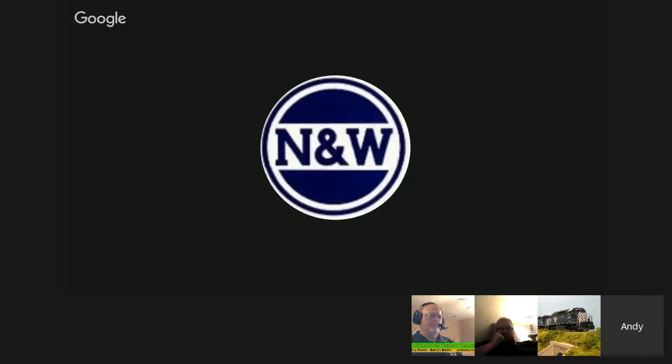However, if wanting to do it from a throttle is pretty important to you, Digitrax will definitely be the easiest choice, no question about it. And I'm not a big Digitrax fan, but it's definitely the easiest solution if that's important. Well, even if you're using NCE, you could just plan on using NCE compatible switch decoders or accessory decoders like the Switch-It, Switch Cat, etc., and just plug them into your cab bus. Absolutely. And then use the Digitrax bus on the PR3 or LocoBuffer just for signals and block detection. That way, none of that interacts with your throttle.